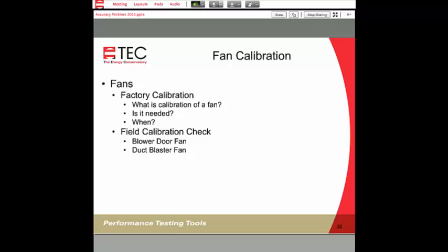Another question, does the temperature of the gauge storage affect calibration? Generally not. We do have a storage value that's listed on our specification page, so we know that over time at a particular storage value that it's not going to harm it. One of the things about the DG700 is that it does have an LCD. LCD stands for liquid crystal display, so there's only so far you can go. You can't go to -40, that's not really a good number, but under most circumstances, the temperature is not going to be affected for most people.